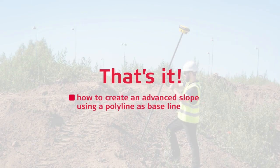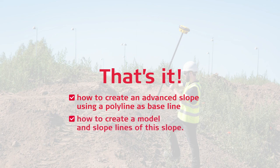That's it. You have learned how to create an advanced slope using a polyline as baseline, and how to create a model and slope lines of this slope.